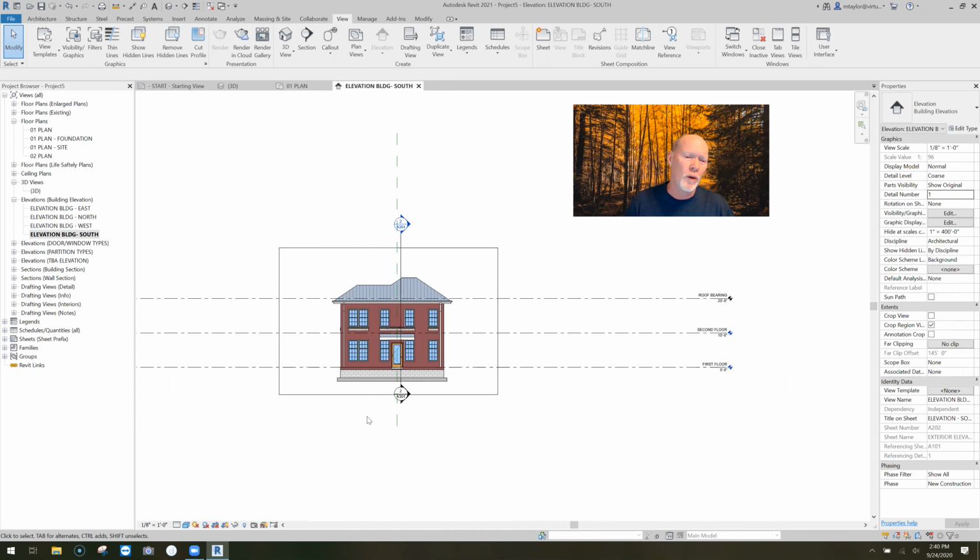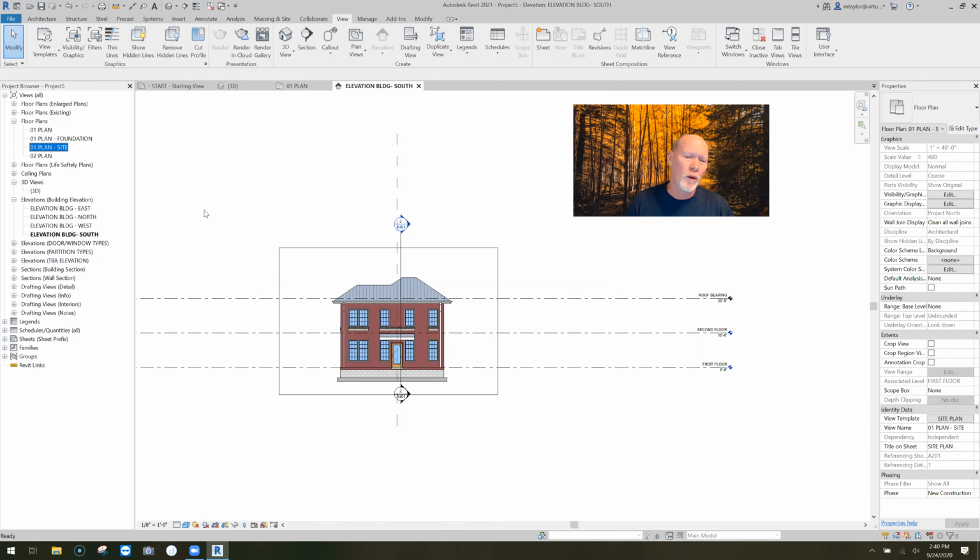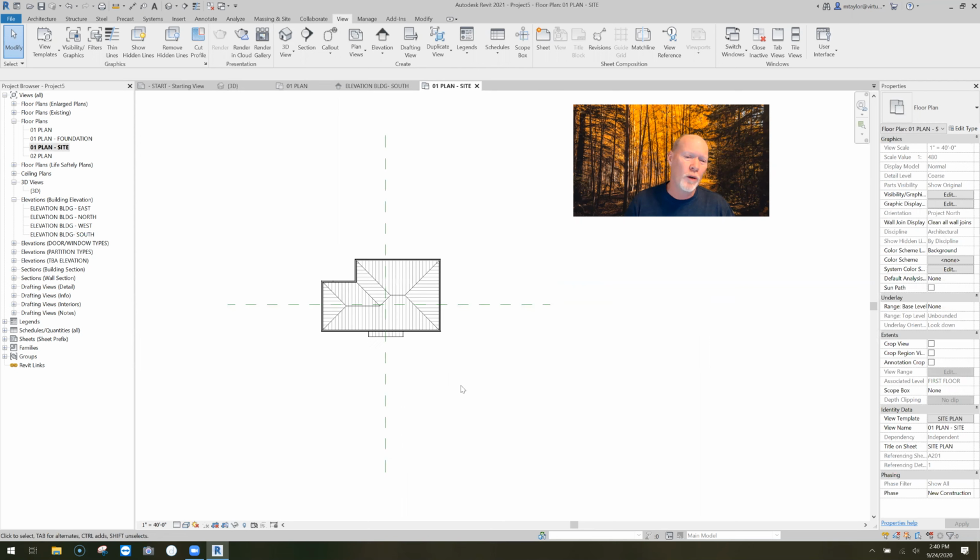You really want to just go to the site plan, which is here, and you feel like just drawing it with lines, right? But you know that you're going to run into issues. If you just do it with lines, there's going to be problems. So if your site has topography on it, you should go ahead with real Revit topography. But if you are on a flat site, just use lines. I'm serious. Don't even worry about it. And you heard that from me.